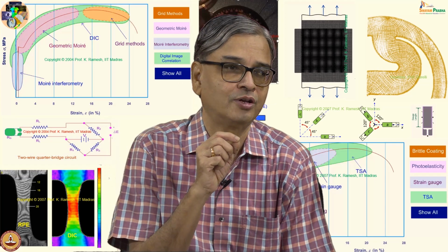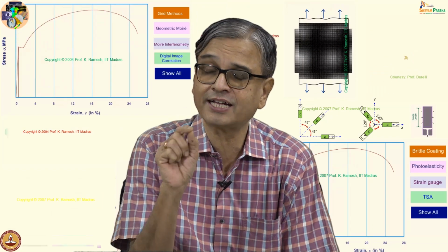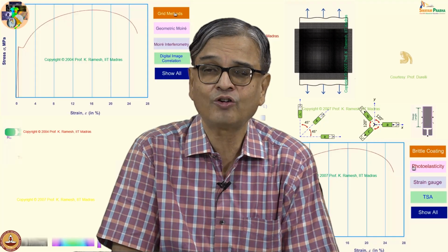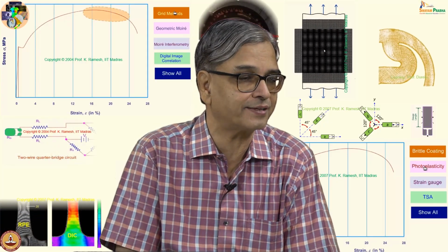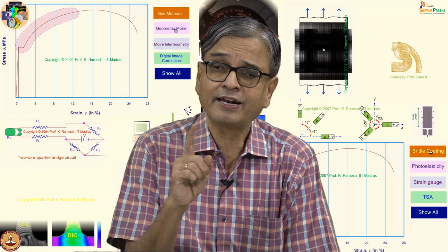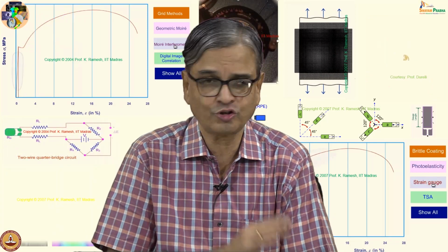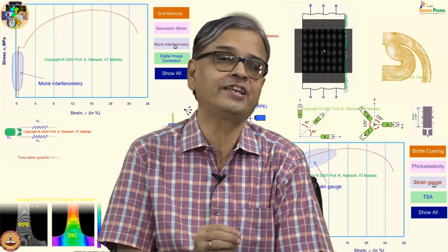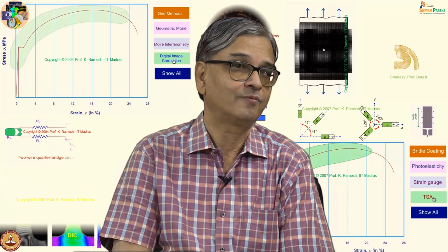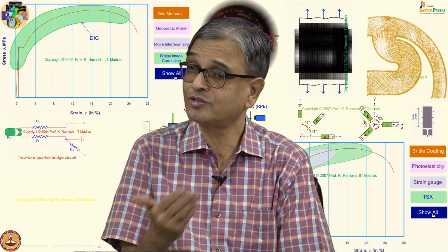First thing is you should know how to find out what is the load applied on the system. So, you take a square element, draw the strain or stress acting on that, whichever way you can do it. Make a mistake, no problem. And I have already told you a strain gauge can measure only axial strain. The question here is, how do I use my strain gauge to measure what happens in torsion? In what way do I have to align my strain gauge when I want to make the measurement? That is also very important.